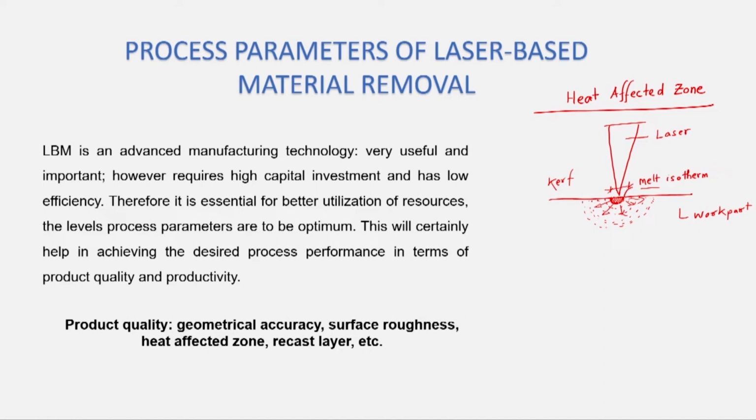The degradation may be a few microns or a few millimeters inside the work material. That depends upon the thermal conductivity of the work material, the power we apply on the work part, and the duration for which we apply the power, that is the density. Density and thermal conductivity both affect the generation of the temperature.